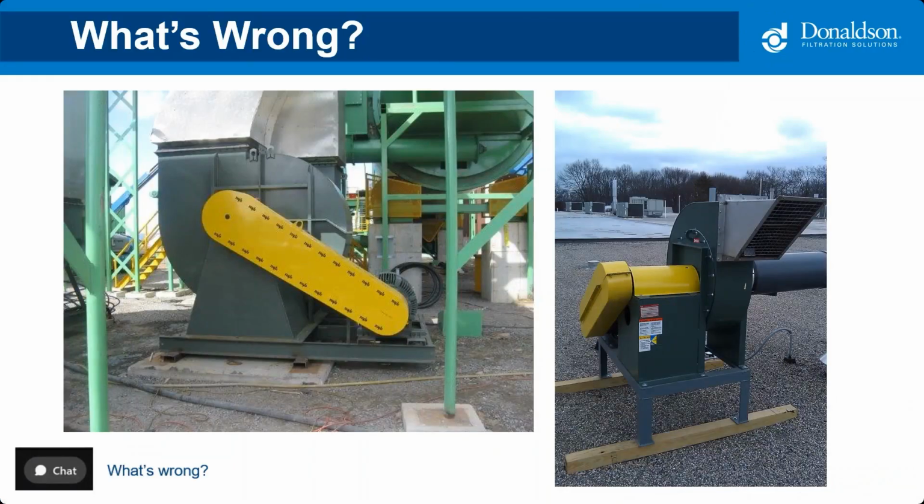What do you think's wrong in these pictures? Okay, we're getting some responses now. Questioning the vibration isolation. So yeah, improper mounting, bad mounting. So looks like most people are turning to the base and the mounting. Yep, there you go. You guessed it. The one on the left there was a nice try, but we could have poured a little larger slab in this case. You do want to support the entire unitary base or the entire fan base, however it's configured.